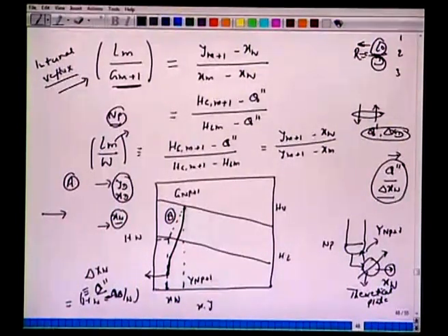Now, you can take another tie line, that line will now correspond to Np. So, notice the difference, we started this way, we had the first tie line for the partial condenser, that was C, and then onward whatever we had, 1, 2, etc. Here we reach Np, okay. And once we reach Np here, then again we can keep on reconstructing this point. Now, Np which corresponds here will correspond to L_Np.